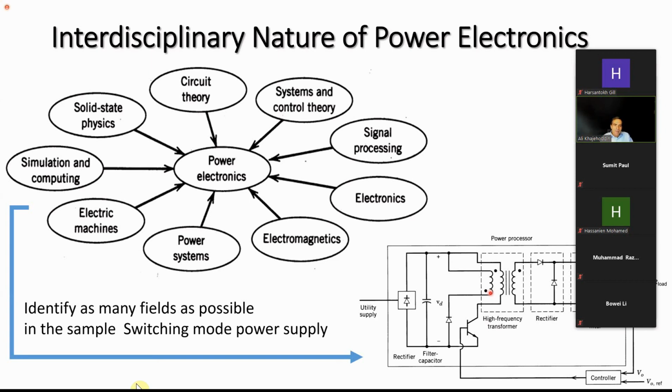But magnetics, you have to custom design for every circuit, because the current level, power level, voltage level, frequency, everything will change the magnetic design. And that's why the variations are so many that they can't just give you all different possibilities. There are some pre-designed magnetics, but they're not very wide.